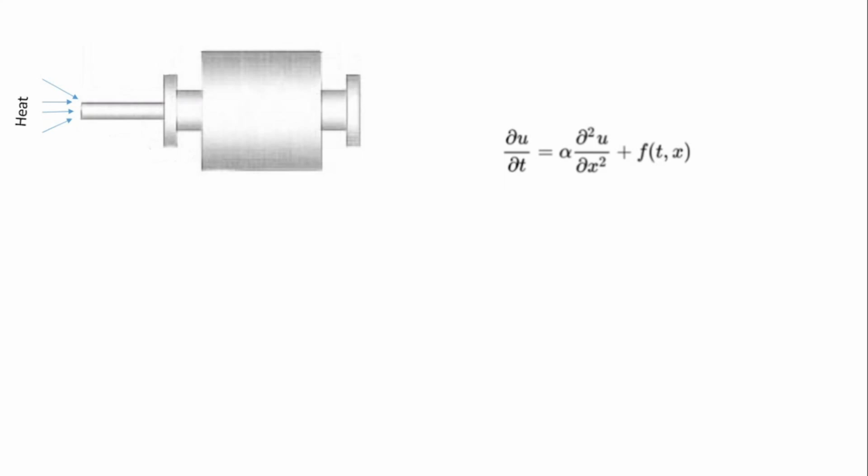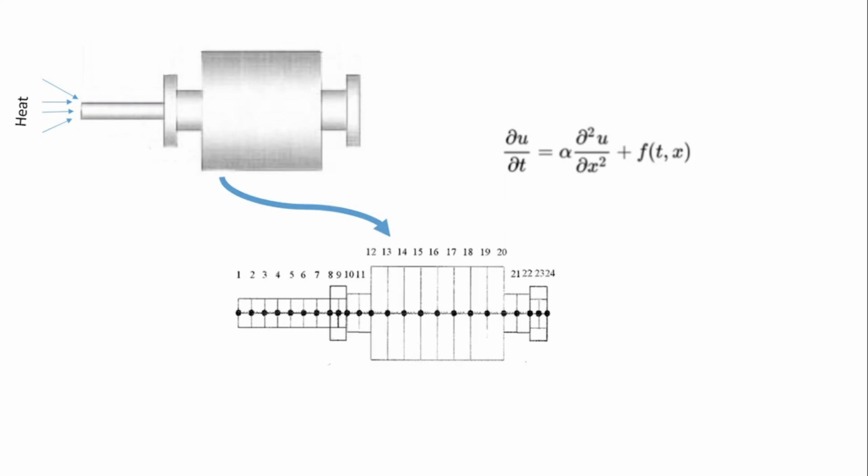And the next thing to do after this is to get your geometrical model. You mesh it. To mesh means you break this into small elements. For this case, we want to say this heat is going to move in a straight line, so let's break this into small straight lines. And once you've done that, you've meshed. Then the next thing to do is to get what you call a trial function. I said earlier that trial functions are primarily polynomial equations. For this case, because it's a linear model, we can say this equation will suffice.